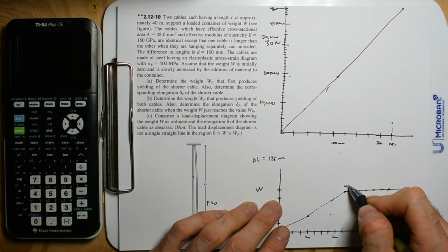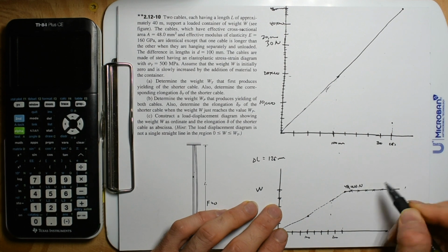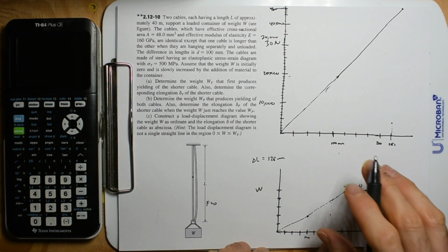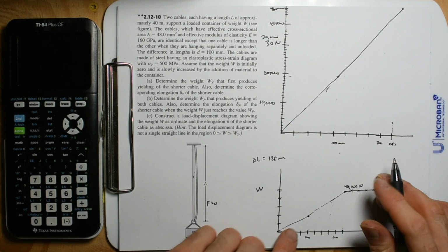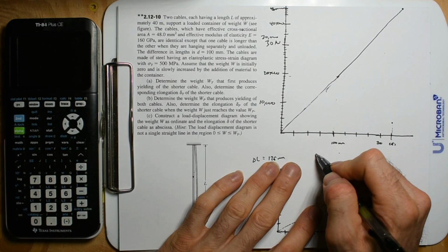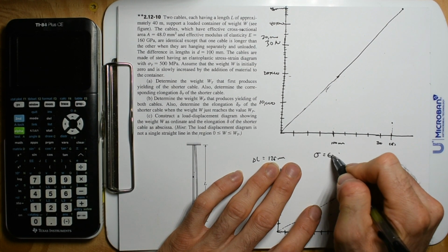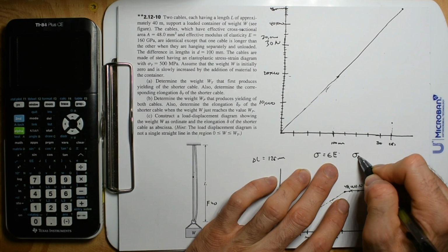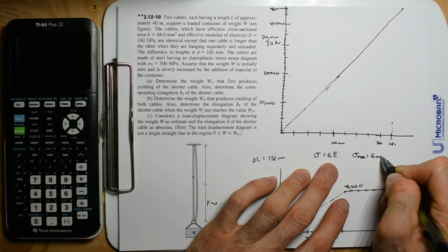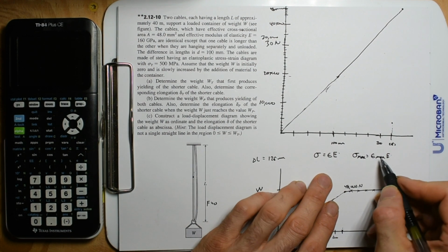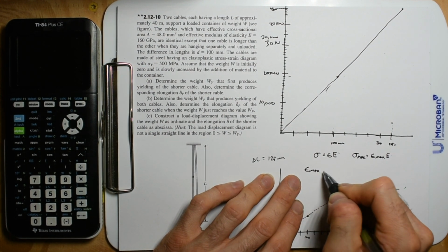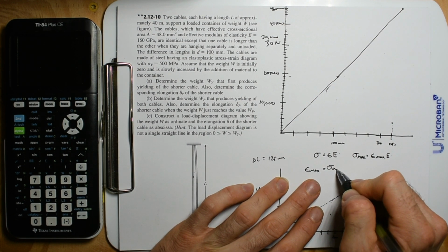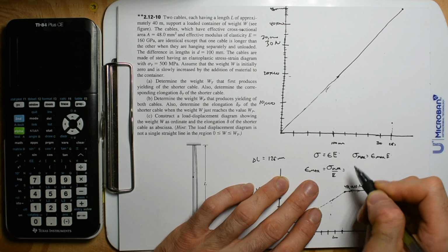So this is going to be 48,000 newtons. And again, to make this make sense, to put a full perspective on it, we said that stress is equal to E times strain. And then we rearranged, and we said, hey, stress max is equal to strain max times E, where E is the constant. Let's rearrange for strain max. So this strain max is equal to stress max divided by E, and we just did that.